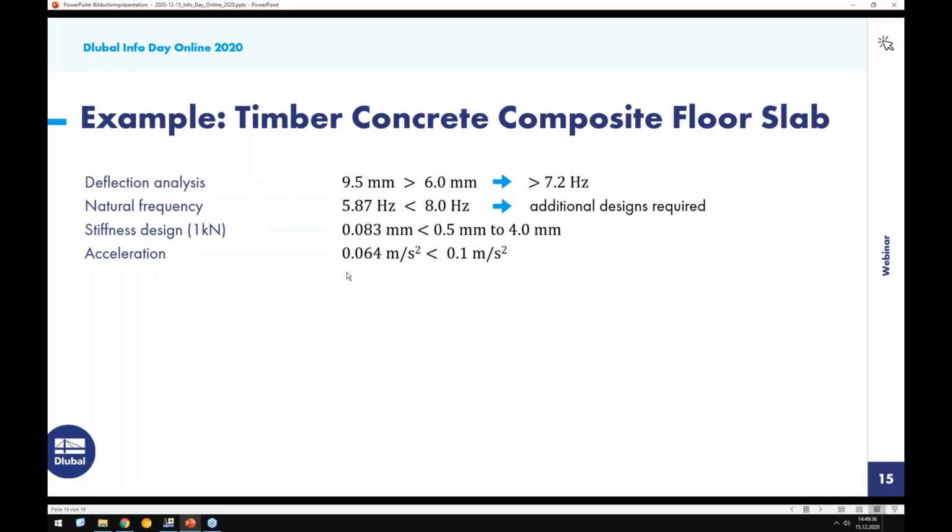There are tests showing that the velocity check done in the Eurocode is actually not really design-governing anymore, because a typical timber floor is, for acoustic reasons, already really heavy. Therefore the velocity check is mostly never controlling and not important. But the acceleration needs to be checked.